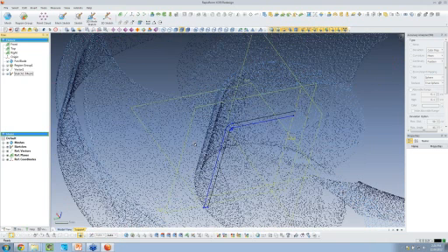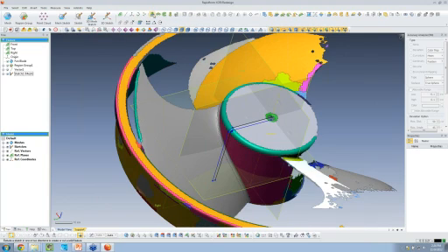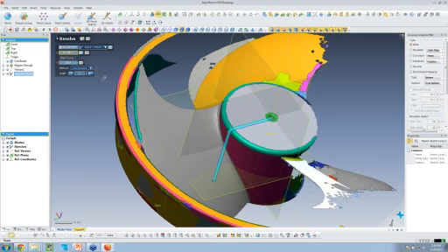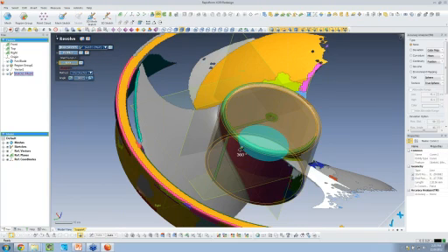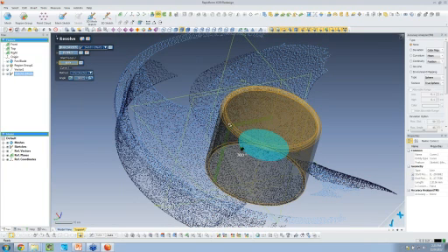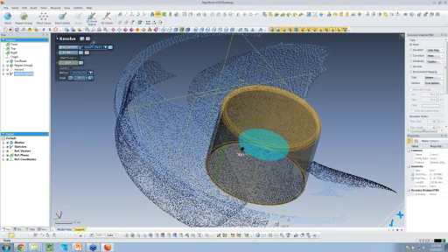So now I can start going into some of my tools, my extrusion tools, my revolves, my sweeps, or my loft. In this case, I'm going to do a revolve. It's asking me what my axis of the revolve is. You see it automatically found that, and it went ahead just like it would in any type of CAD software. It made a revolve.